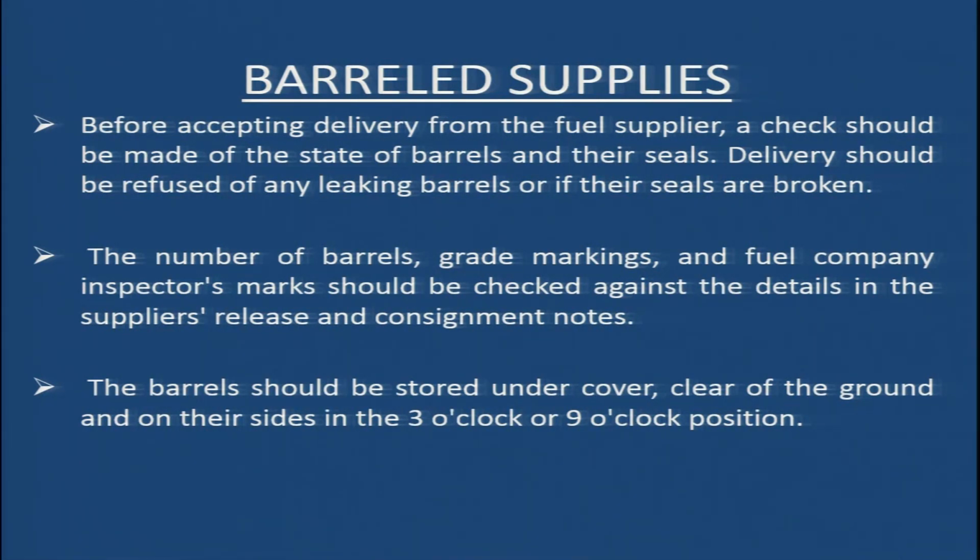The number of barrels, grade markings, fuel companies, inspectors marks should be checked against the details in the supplier's release and consignment notes. So, all the papers which are being given while taking the fuel, these grade markings, the fuel company inspectors marks, inspection reports, they should be checked.